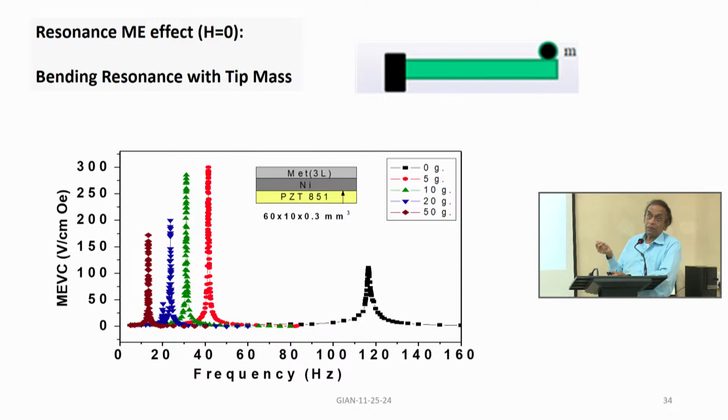You can manipulate the resonance, and based on what kind of magnetic field you are going to measure, you can tune the resonance. How do you measure the unknown AC magnetic field? It's rather easy. So, you are going to use two different AC fields. One at resonance frequency, the second one that you want to measure.